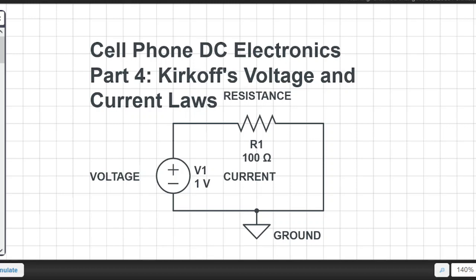So essentially, in this schematic, all of your voltage would drop across the R1 resistor, and anything on the right side, all the way down that line to the ground point, all the way to the negative side, would equal 0. All of your voltage coming off the battery on the positive side is being dissipated through that one resistor.